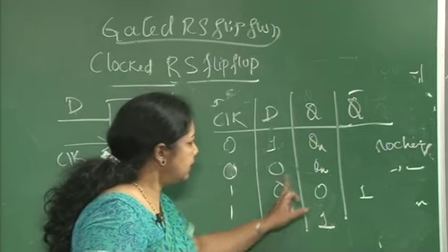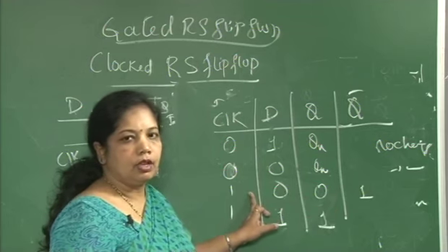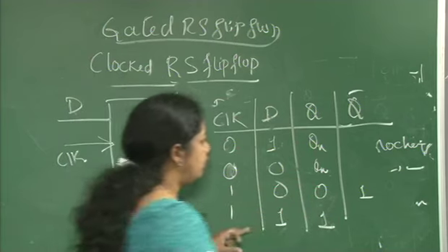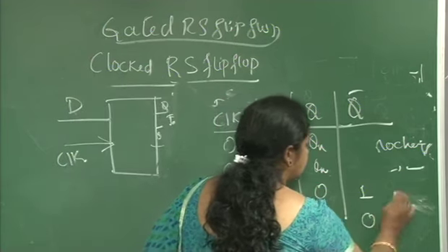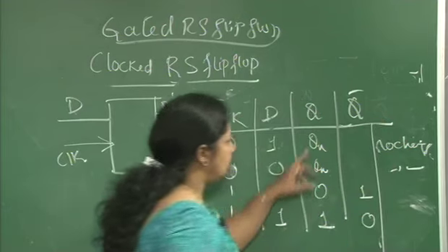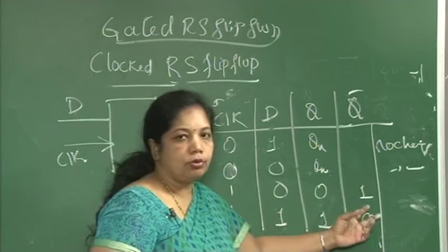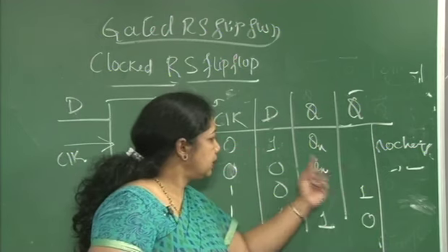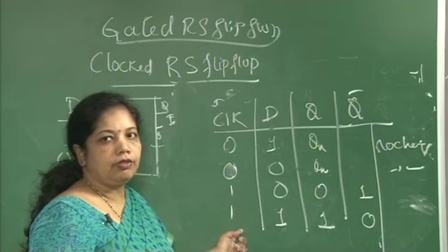So, the same thing is transferred at the output when there is a clock signal. So, this is how the D flip flop works. So, this is the complement. No change condition when there is clock 0. So it transfers to the output whatever input you are giving, whenever I apply a clock. This is how D flip flop works.